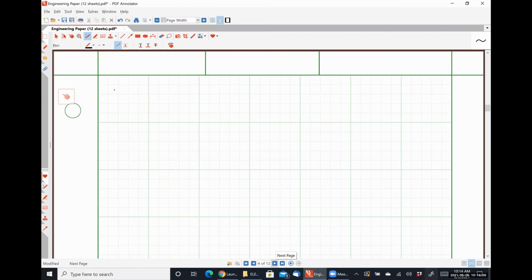Now this is something that we've technically already covered way back when we were talking about the constant gain bandwidth product of an op amp, but now we're generalizing it for really any amplifier circuit, okay? So let's say that I have a one-pole open loop amplifier.